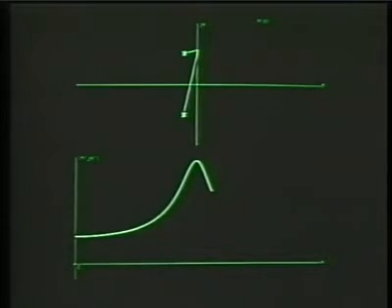From this point, as the frequency increases corresponding to moving further vertically along the j omega axis, both pole vectors will increase in length, and that means then that the magnitude of the frequency response will decrease. For this specific example, the magnitude of the frequency response will asymptotically go to 0.